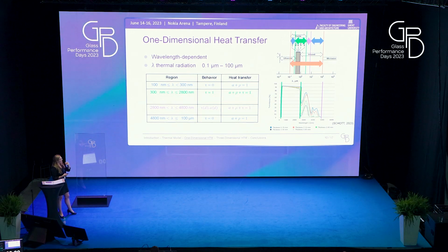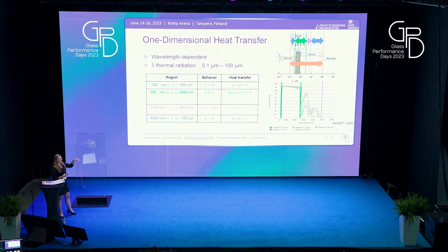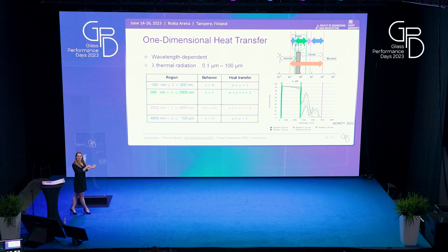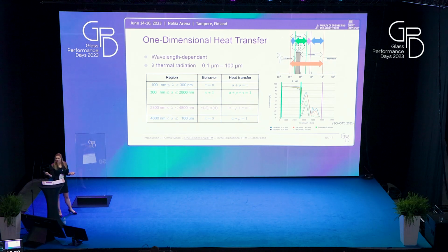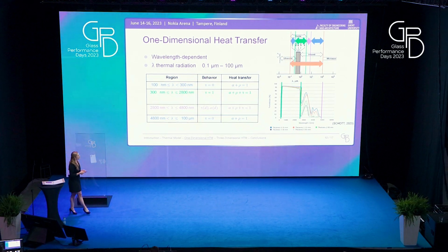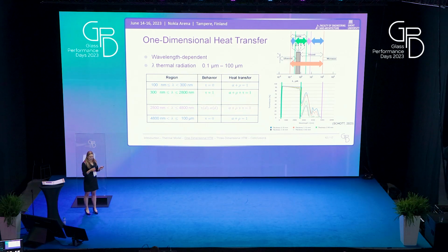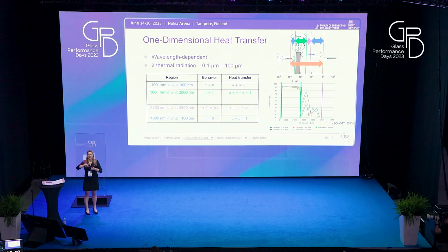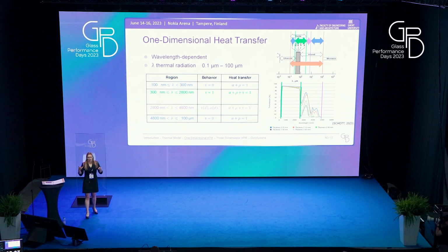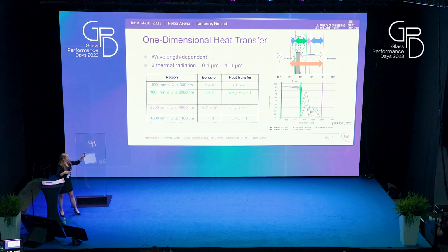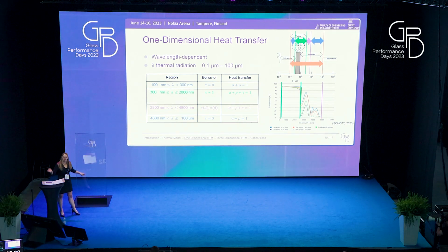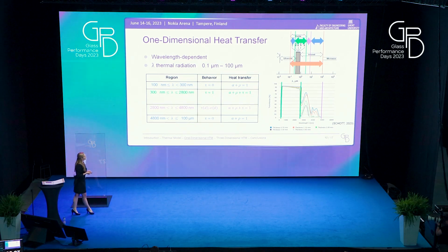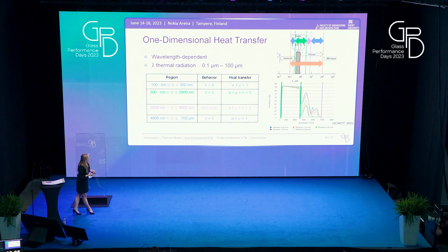And as you can see over here in the transmission spectrum, the graphs also depend on the thickness of your glass. So this decrease of the transmission is also depending on the thickness of your glass. So you have 2 influences over there. And as we know, we have our glass surface, so we have the reflection at the surface and then transmission and absorption. So the reflection basically stays the same. So the change in transmission will give a change in the absorption. So that's the relation that we will basically see in this purple region. Now, it's a bit complex.